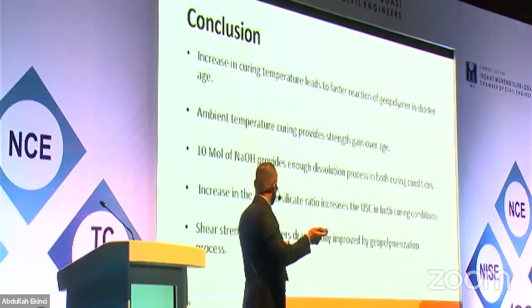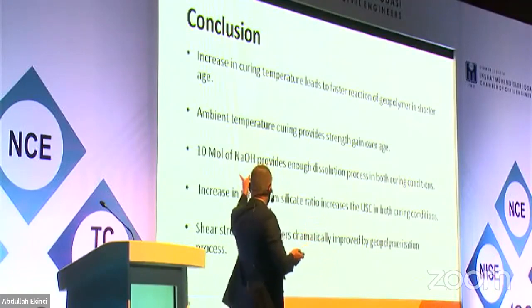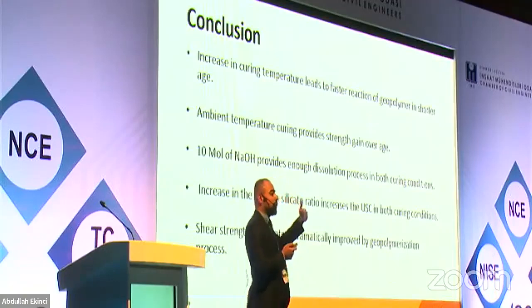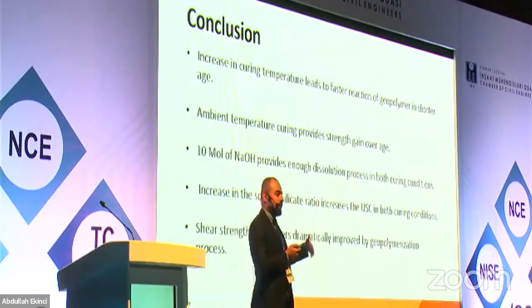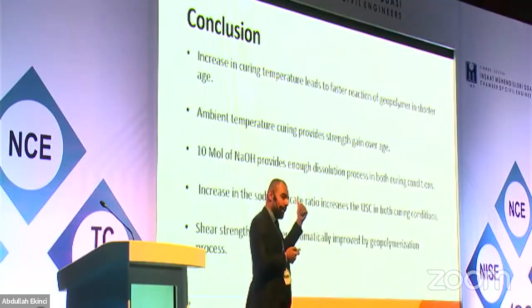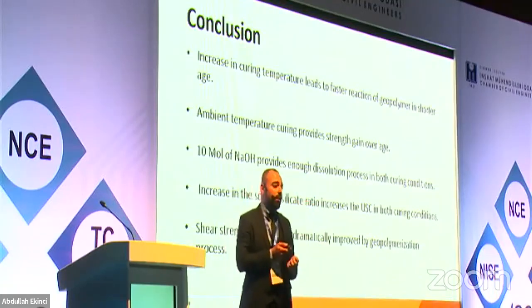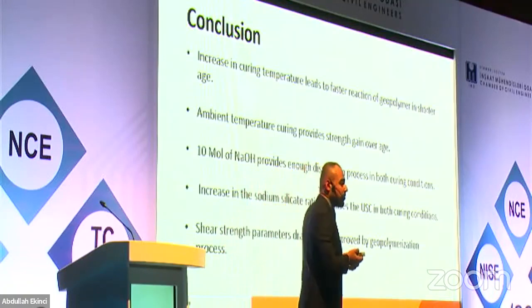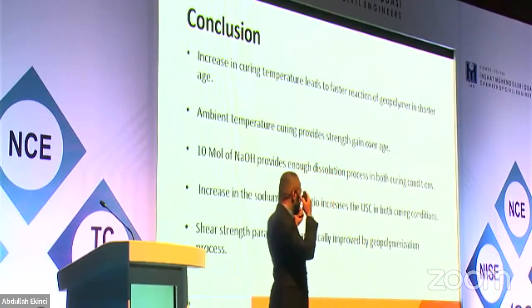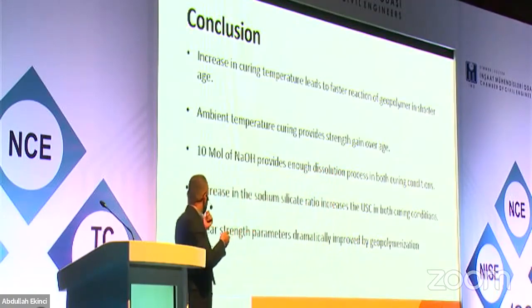whether winter or summer. Well, the ambient temperature that we did was providing and gaining strength over age. So that might be another aspect for a longer period, to see how far the strength is going to go. That's something we can study. Well, not only the strength will be the thing that we have. Durability is one of the issues that we should consider, to see over age what will happen in the sulfate attack and the acid attacks, or to see how this material will behave with age.